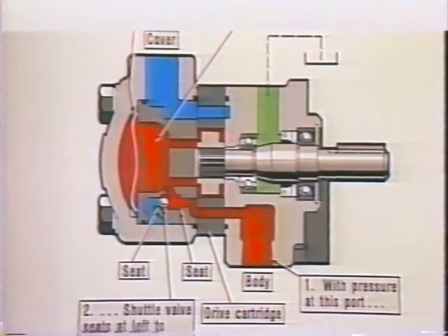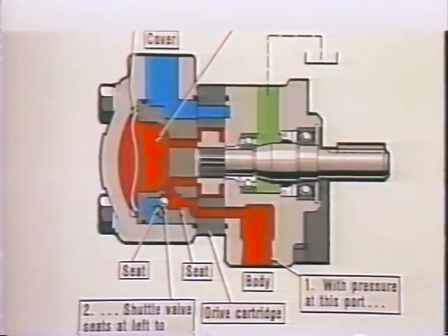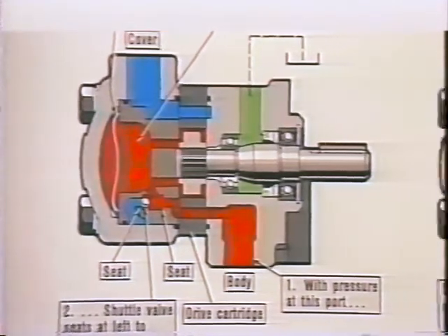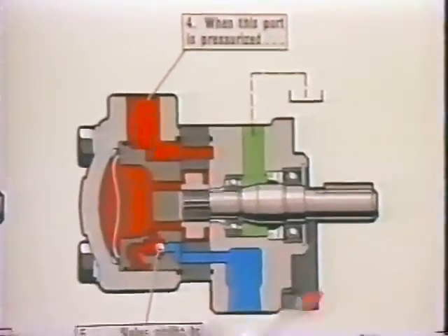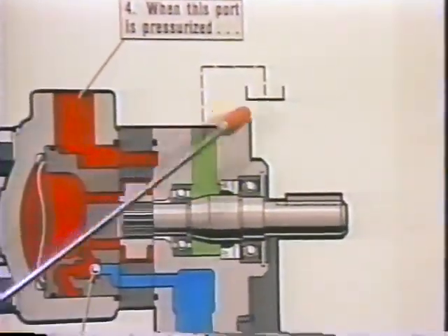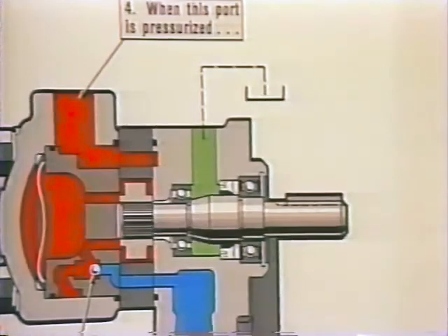That same pressurized oil is also fed through holes in the pressure plate to the bottom of the vanes to help the rocker arm spring hold the vanes out. Because of the reversibility of a motor, leakage oil that collects in the shaft chamber has to be drained externally. We cannot drain the unit internally because at one time or another each port is pressurized.